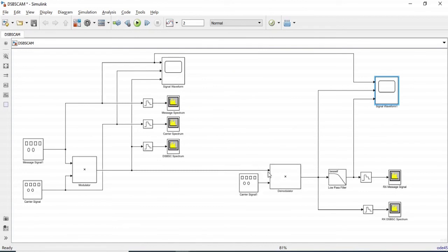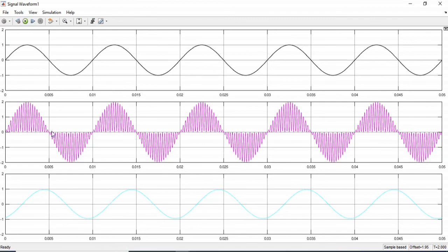So whatever was the input, we multiply with the cos function. So this cos multiplied with the original cos, so we have a cos square. So this is why we have this plot. We have already discussed this in the discussion session earlier as well. And you can observe that there is a low frequency content and there are higher frequency contents within this. So if we use a low pass filter, we can reject the high frequency contents and we can recover the low frequency signal, and this is something that we have done over here.